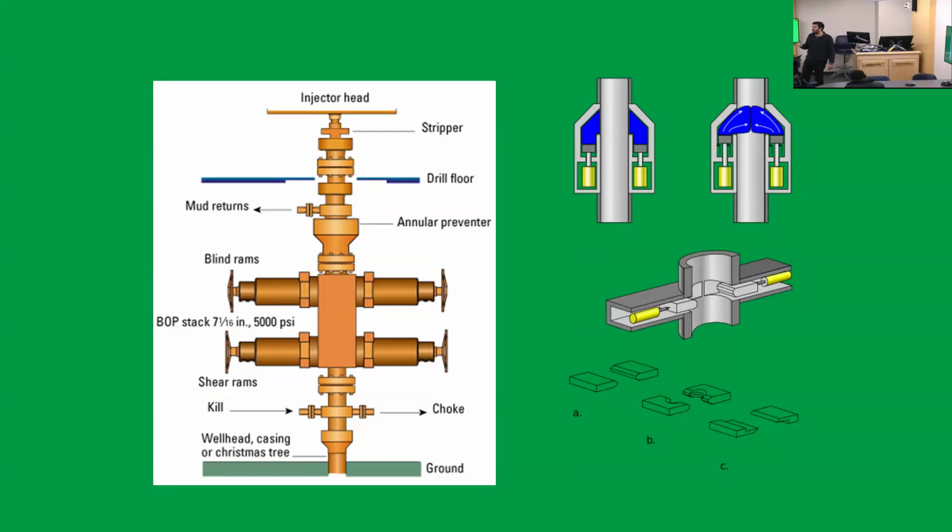The annulus or the drill string? When you get a kick, it passes through the annulus. Yeah. Most of the time, though not always, it's going to be in the annulus. So you care more about securing the annulus than the drill pipe.